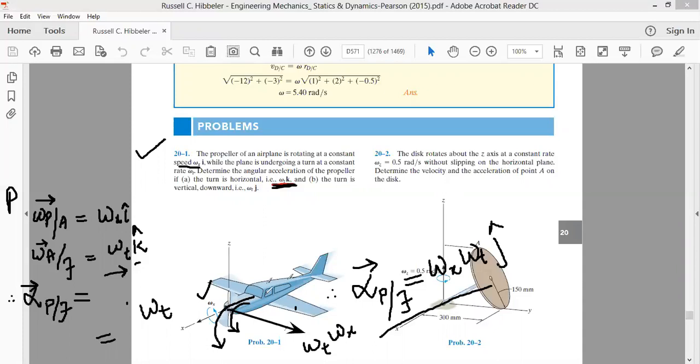What does that mean? That means this entire aircraft will tend to rotate in the anti-clockwise direction. So the nose of the aircraft will pitch down. The nose of the aircraft will go down. This is called the gyroscopic effect. This is the gyroscopic effect of the aircraft. Okay. So what does it mean? It means that an aircraft propeller rotating in an anti-clockwise sense, when the aircraft takes a left-hand turn, makes the nose of the aircraft go down.